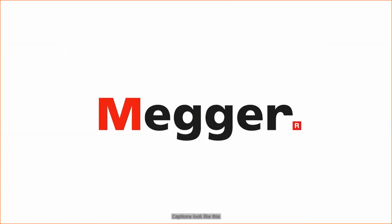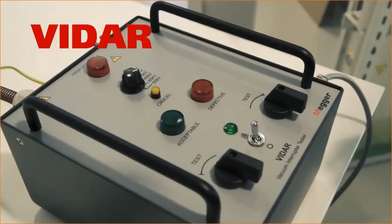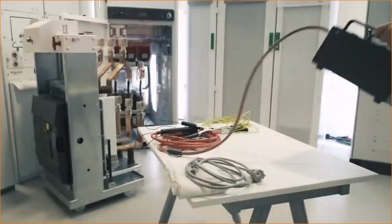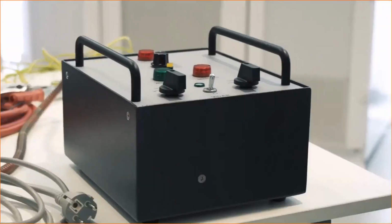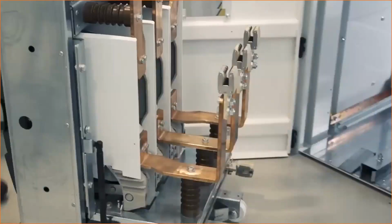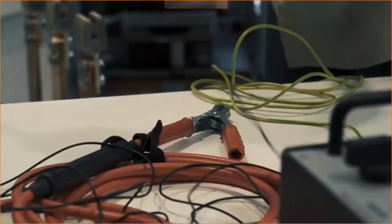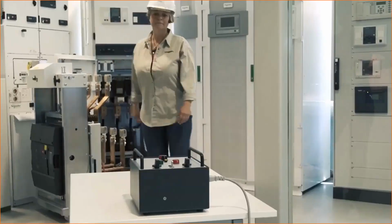Producing high-quality test instrumentation for over 100 years. VIDAR presents a superior alternative to AC high-pot testing. Traditional AC equipment is more than 10 times the weight of VIDAR. Insulation integrity testing is recommended by the manufacturers of circuit breakers and well documented in international test standards such as IEC and IEEE.